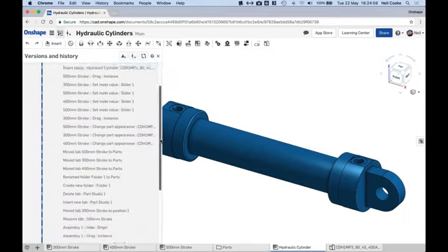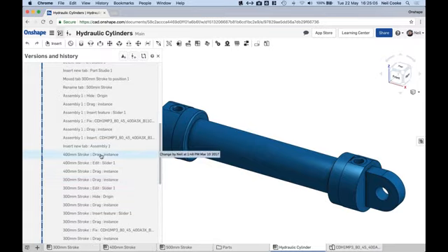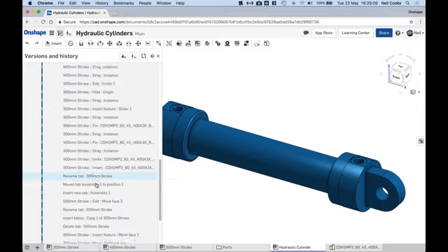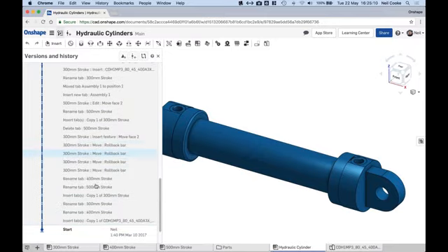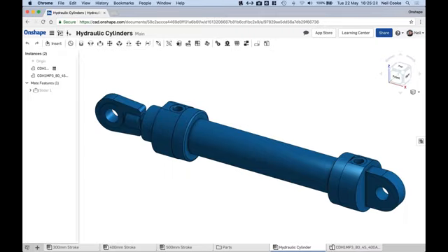But the interesting thing here is the amount of information which is in this document. So every time there's a modification to this, and it could be dragging an instance, or renaming a tab, anything that's done within here is recorded, and so you can see I did this back on March 10th last year. You can go back to any point in time and see what it looked like at that point in time. So in the scenario I mentioned earlier where autosave overwrites everything, that kind of thing doesn't happen in Onshape because everything is recorded and you can go backwards and forwards, giving yourself an unlimited undo redo for the lifetime of that document.